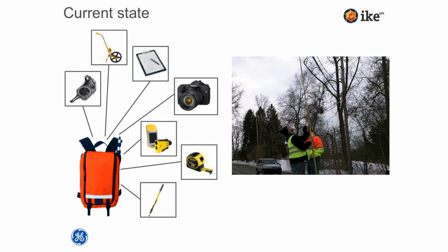We've depicted a typical scenario here of a manual methodology for collecting midspan, but with our all-in-one device, you can either limit it down to one person, or at least you're out of harm's way, so you can take a picture of the wire and calculate the midspan without having to get in the line of traffic. This piecemeal approach in the current state doesn't afford us the ability to take all the data and draw it together digitally, so it's ripe for transposition errors or requires a lot of manual entry.